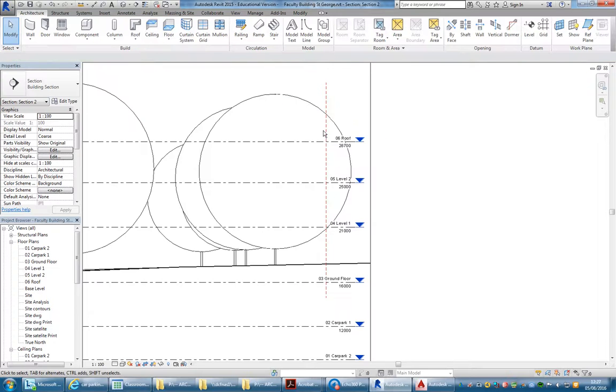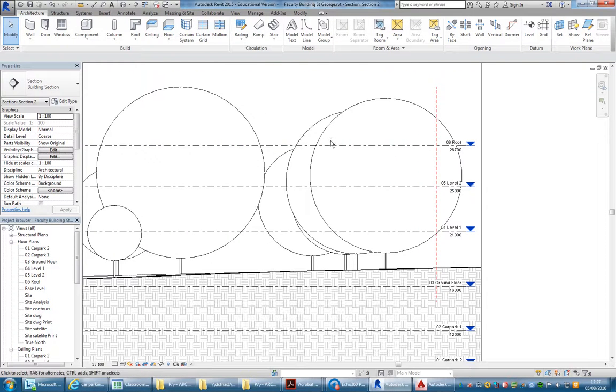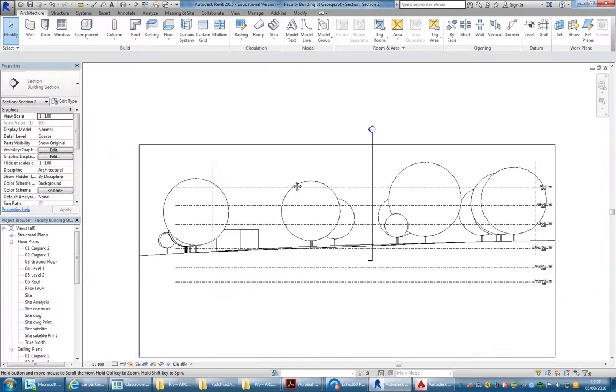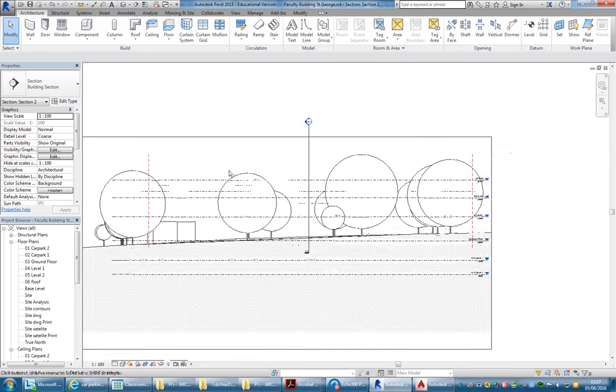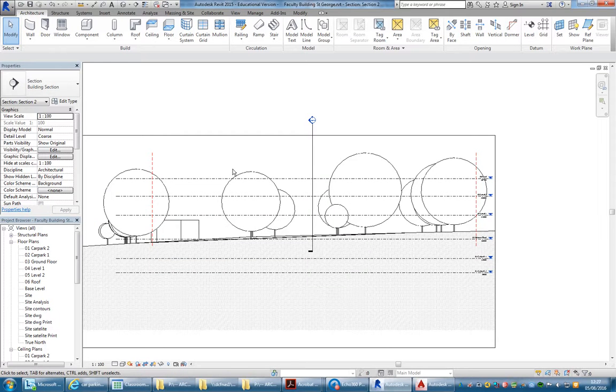And if you have balconies and other things where it's set down or set above the main floor level, just offset them from that level. Don't always make levels for all of those extra floors that are based on another main floor level or that are close to one.